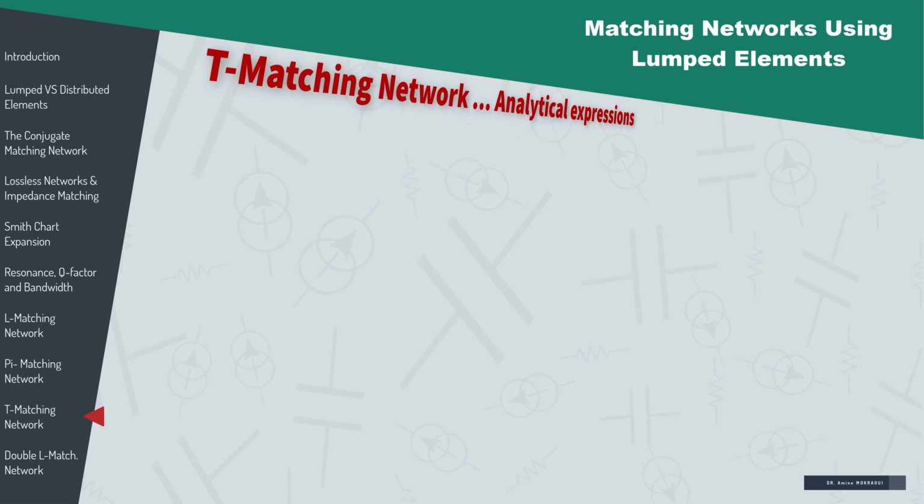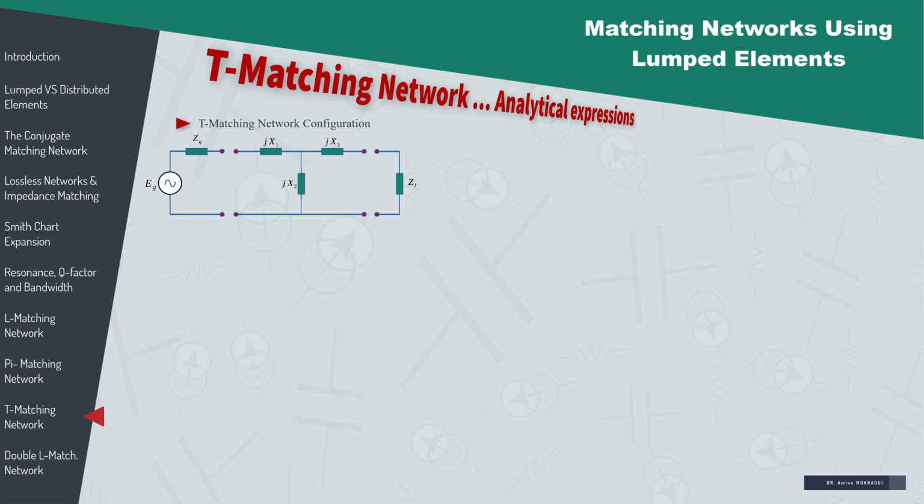If the designed pi matching network doesn't bring a realizable circuit because of component values or because of its frequency response, an interesting alternative could be the T matching network. It comprises three reactances, x1, x2, and x3, in a star or Y configuration. Through Kennelly's theorem, we can derive the T-matching network directly from the pi-matching network. However, the obtained T-circuit will not behave as the pi circuit does. Thus, we must develop the T-matching circuit from scratch, just the way we did with the pi-matching network.